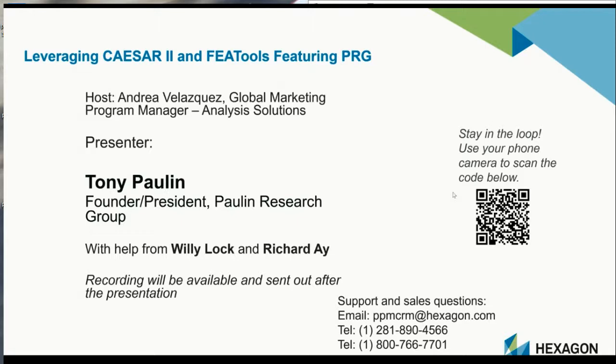Willie, maybe you can answer that one. Yes, we do have a comparison in the Caesar 2 FEA translator. Once you run a quick translation, it will give you the comparison from B31.3 SSI 0.75 times small i against B31J and FEA. There's also a panel on Nozzle Pro and the FEA Tools that lets you bring up a spreadsheet, and you can put in any intersection you like, and it will compute the SIFs and the SSIs for both branch connections and bends, and you can see the comparison of the new data versus the old data.